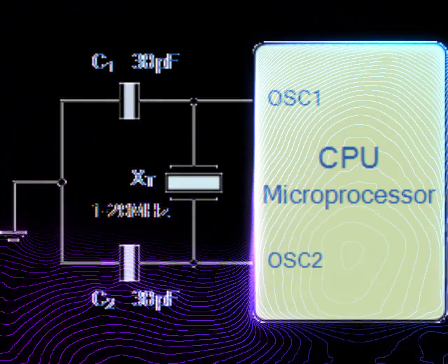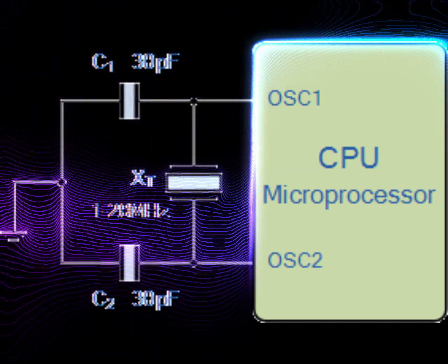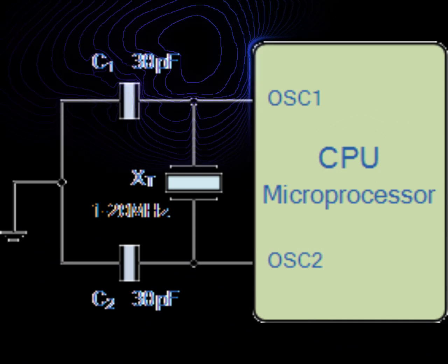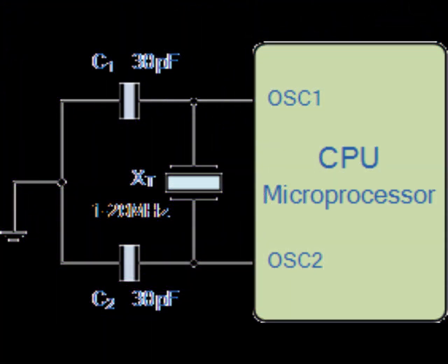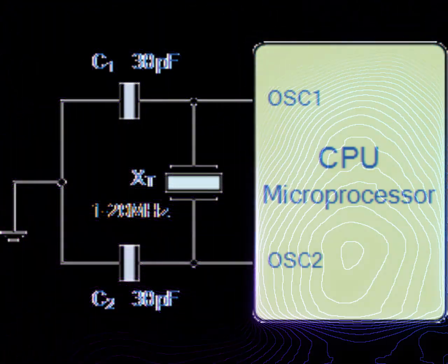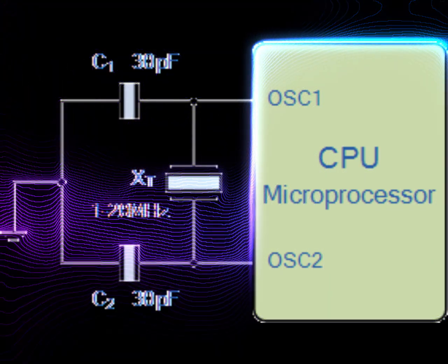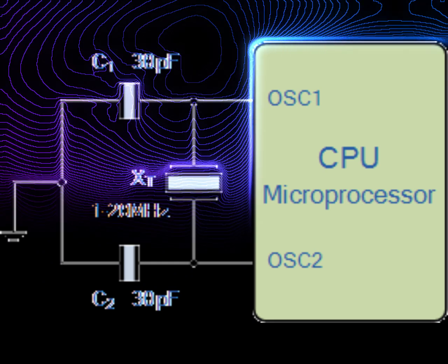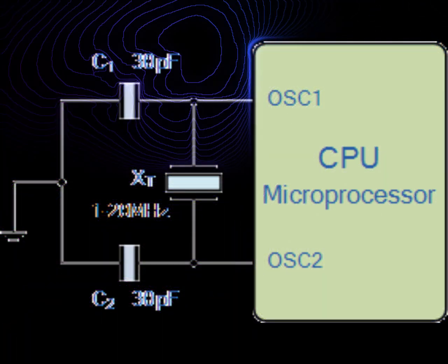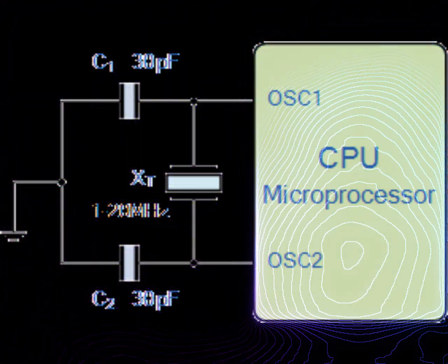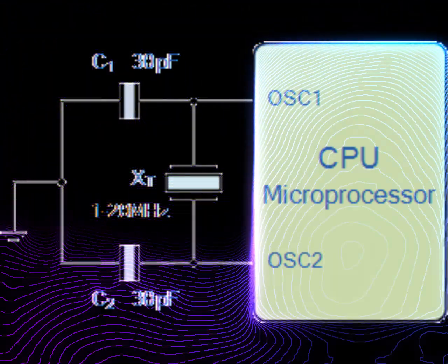With this small thickness, resonance at very high frequencies in the fundamental mode becomes possible, which is not available using standard AT-cut blanks. Consequently, high clock frequencies can be generated without the need for a PLL multiplier, resulting in lower phase noise than PLL multiplier solutions. Manufacturing of AT-cut quartz crystals.